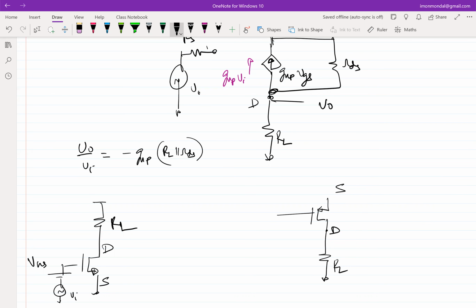Some higher potential which doesn't change. That's what incremental short means: a constant potential. Constant includes zero. In the case of an NMOS, zero would have been fine because the source is supposed to be at a lower voltage. In the case of a PMOS, zero wouldn't cut it. You have to go to a higher voltage, and the highest voltage you can find on the chip is VDD. So connect to VDD.